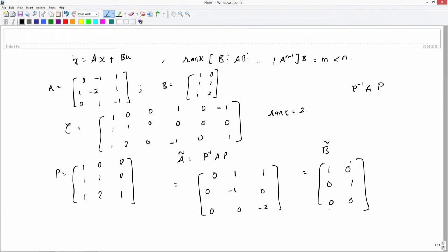Let us carefully look at this. Say I write a system like this: x1 dot is u and x2 dot is minus x2. It can be easily checked that this system is not completely controllable, because there is no direct control entering the x2 coordinate. So here I can clearly see which of the two states is not controllable: x1 is controllable and x2 is not.